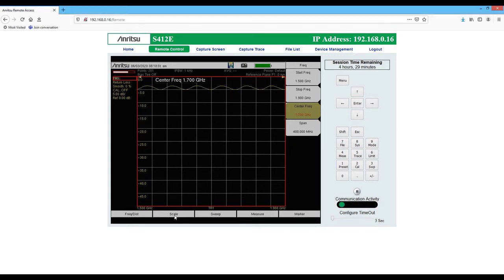As far as the scale goes, 0 on top, -50 on the bottom, that's a perfect scale for return loss type measurements. If it were a different type of measurement, the scale would be different and we'd set it up differently. If it were a VSWR measurement, for example, 1 would be on the bottom, and then we would set up our scale above that. I normally use 1 to 10 or 1 to 5, but that's up to you.